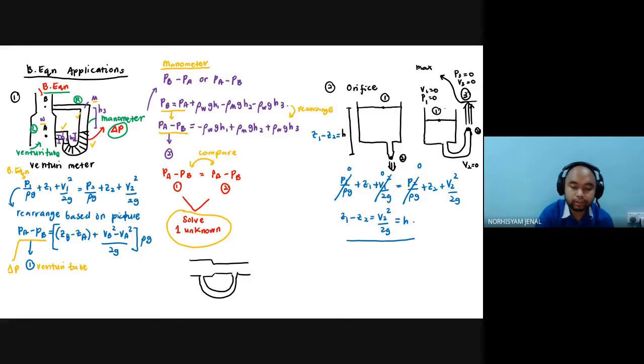All right, like this, for example. We may have the flow coming in like this and coming out like that. This is point A, this is point B. The different thing about this is the manometer is down here. For this part, A and B are at the same elevation, so you can cancel out ZB and ZA. The one we did just now has different elevations, so we cannot do that.